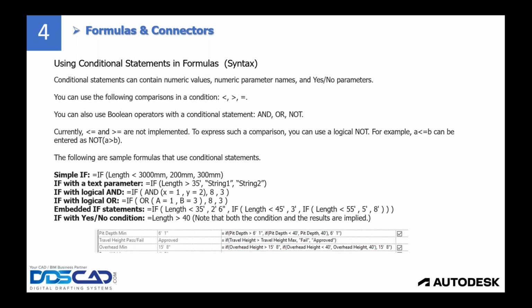Now, not only can we create formulas, we can also create conditional statements so that Revit can make decisions inside the family, whether to go one way or another way. And this is very typical, the yes and no, if this happened, then I'm going that way, and if this is not happening, then I'm going another way. All of these little things that we played when we were kids, yes, no, yes, no, and so forth. So those conditional formulas in Revit are very simple, really.